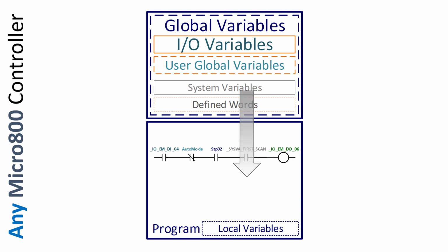And so the next one, system variables first scan. Now never mind what this is. Well, I'll just tell you. This bit is true for one scan and one scan only when you go into the run mode.